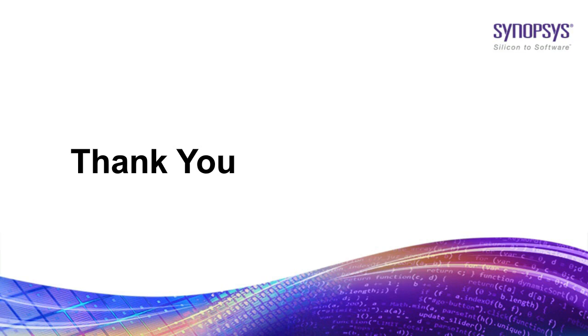So to summarize the DFT side, at the IP level, we believe that 1500 is the best solution. Today, there are many IPs that come with that already. In between the different levels of hierarchy in the SoC, we use IEEE 1687. At the top level, we use 1149.1 as DFT.